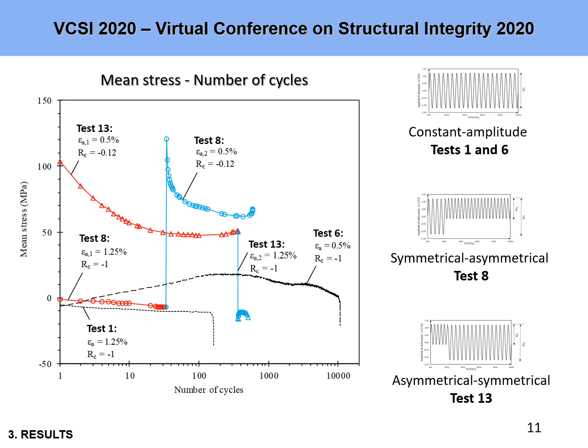With regard to variable amplitude tests, loading sequence considerably affects the mean stress level. In test 8, the mean stress at the first stage of the loading sequence is similar to the constant amplitude of test 1, conducted at the same strain amplitude and the same strain ratio. Nevertheless, when the loading history changes, the mean stress rises and decreases rapidly towards the trajectory described by the first stage of test 13, performed at the same loading conditions. The convergence was not attained because total failure occurred.